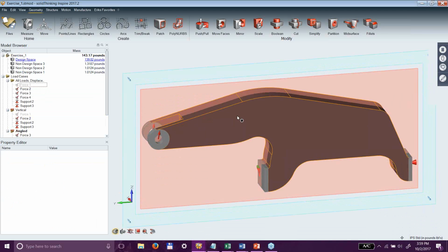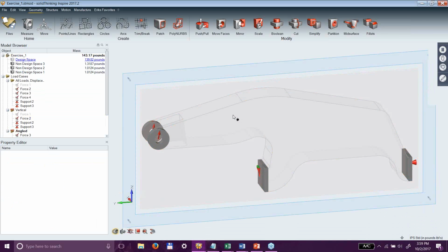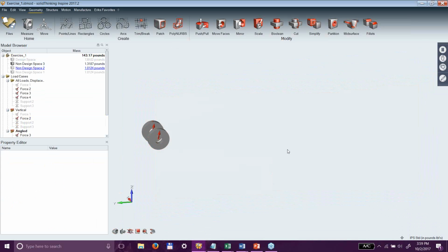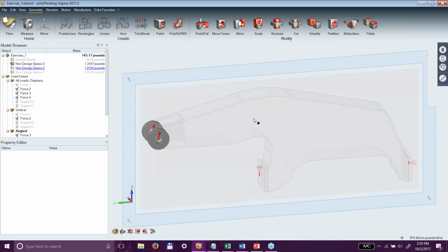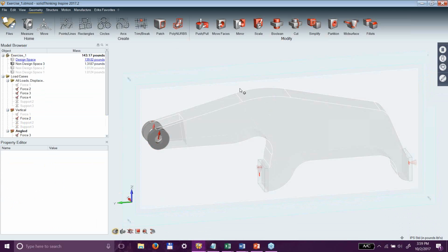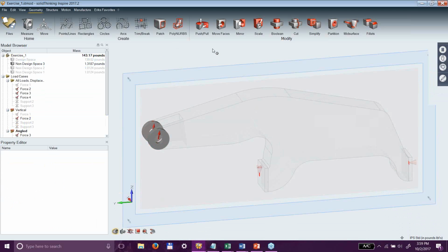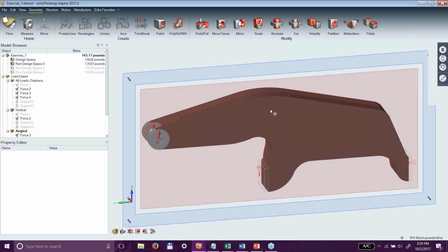That indicates that anything that I click on, say that solid, now goes hidden. And when we're in the hide show mode, it shows up as a wireframe. But as soon as I right click to select to get out of it, those features go hidden. If I re-enter it, and if I hold my shift key down, you'll see that that little black star modifier has changed to a white star, and anything that I select now turns back on.